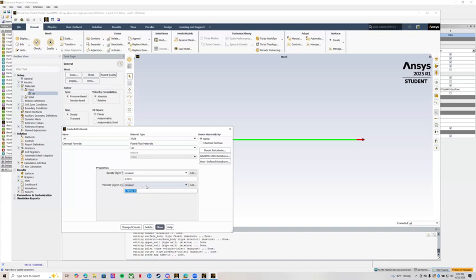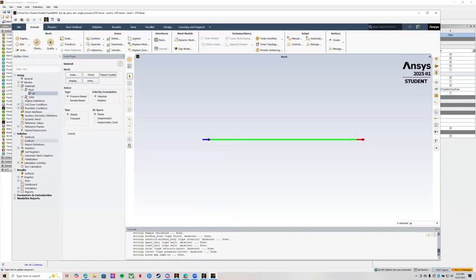We're more towards a laminar flow. So our viscosity is going to be 1e-5 kilograms per meter-second. And then we're going to go ahead and change that so that it updates here. We want that to be 1. Boom. Once we press change and create, you can go ahead and close this part.